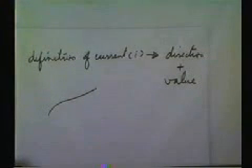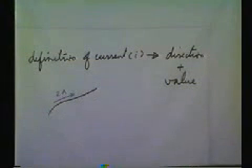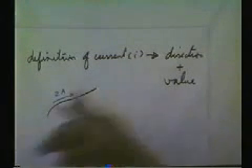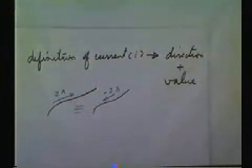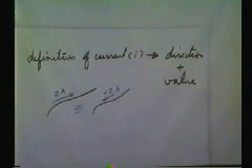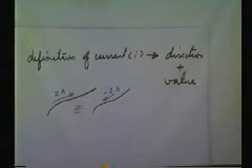For example, you have something like that, and then you say, well, the current, you can say this is 2 amp, or for this one, you can say this is minus 2 amp. These are equal. Because the current flows in this direction, the quantity is 2 amp, and this one says minus 2 amp going this direction, so actually the real one is opposite.